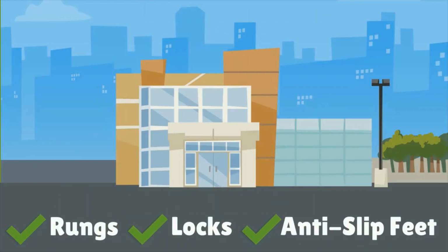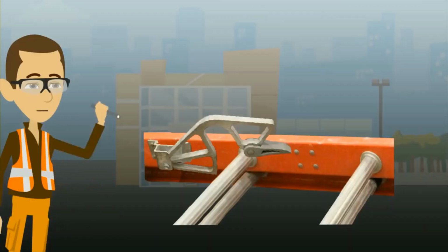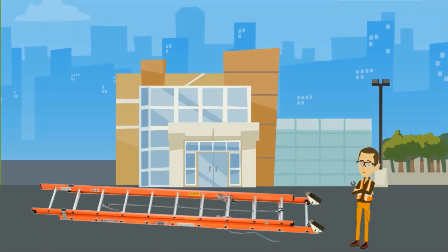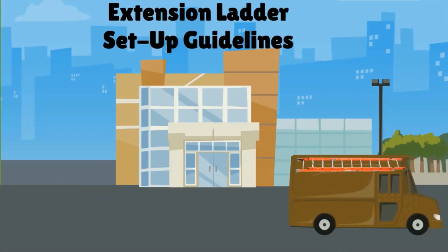Ask yourself these questions as you inspect the ladder. Are the rungs in good condition? Do the ladder locks function correctly? Does the ladder have anti-slip feet? And, if so, are they in good condition? Before using a ladder, follow these setup guidelines to ensure it's safe before climbing it.